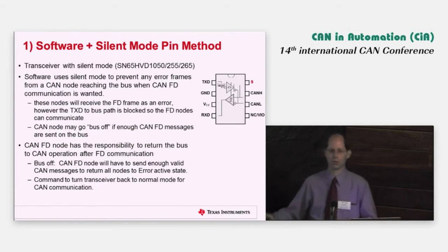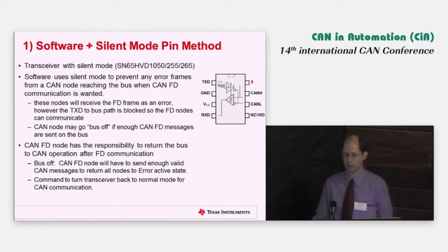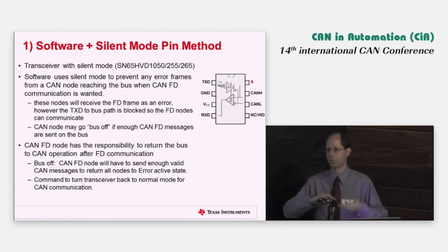Obviously, it uses essentially hardware that exists today. There's no new invention in terms of that. It's all pretty much on the software and application levels within the system. But one of the big disadvantages is the long latency to turn the bus around from one communication method, FD, back into CAN. Not the most efficient way to change the communication scheme.